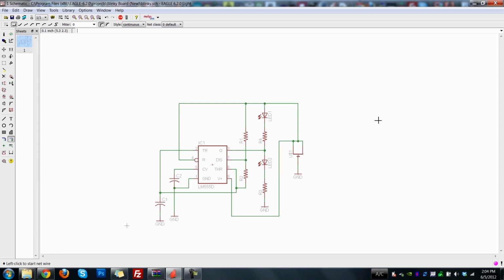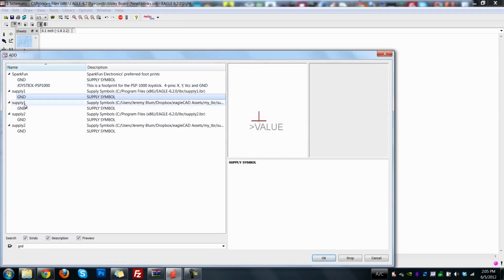Okay, so I've finished connecting all the parts, but this still looks a little bit messy. So we can do even a little bit better in Eagle. Just like we added the multiple grounds, we can also have a unified source so that we don't have to connect all the positive terminals of the battery to everywhere. So let's go ahead and implement that. These are just steps that aren't necessarily required. It's going to work exactly the same in the board view, but it'll make the schematic view look a little bit nicer. So let's cancel this search.